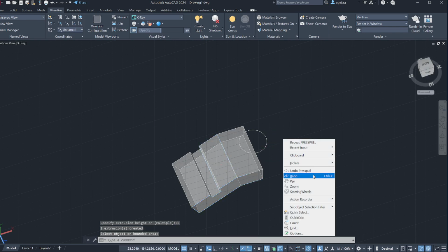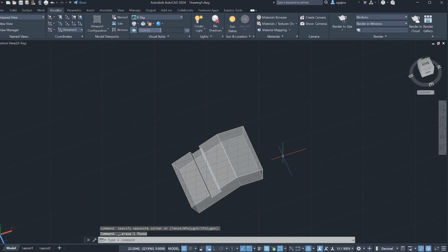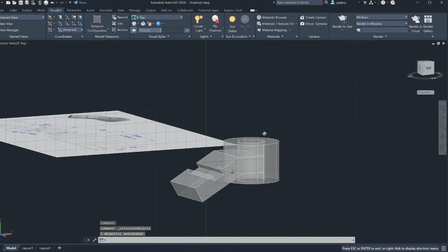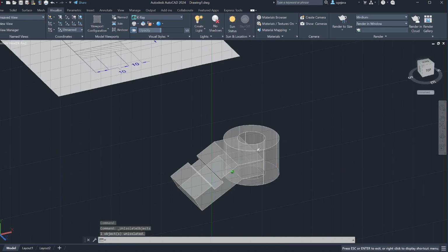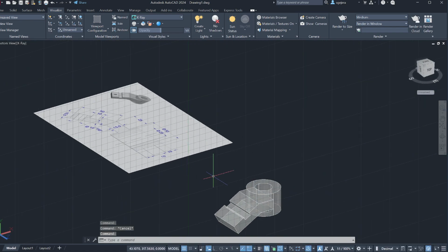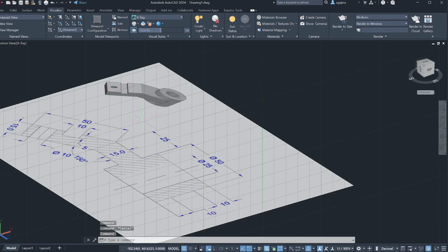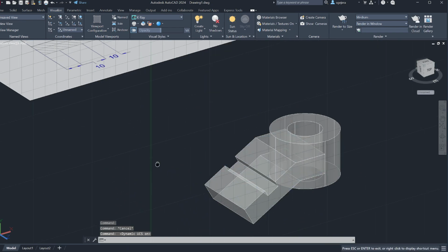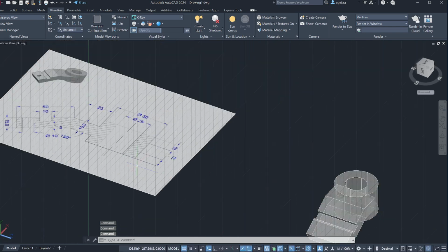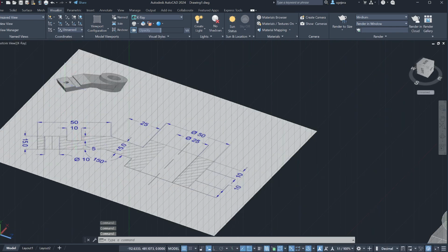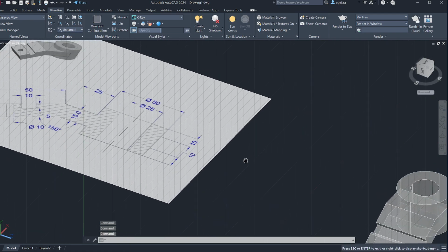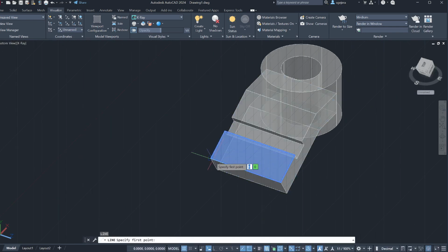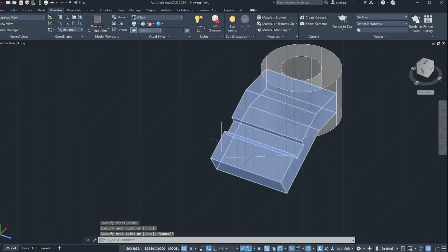Okay? So, if I end object isolation, then probably pwede ko na i-delete to, no? Itong guideline ko na to. So, do end object isolation and that should fit perfectly, no? Parang ganyan. So, we're almost done. Gawin na lang natin is carve out the hole here and parang useful lang magiging UCS dito, no? Find natin si center of this object. So, probably the easiest way to find the center is to create a line. Parang ganyan. And this is just a reference line, no?